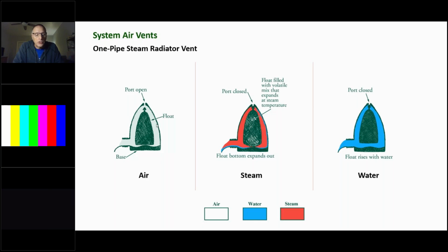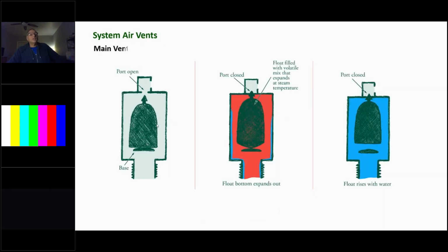If you show up and your pressure control is set at a 2-pound cut in and a 4-pound cut out, it'll start up fine on the first cycle of that boiler. As it starts up, the vent closes because it's set at 2 to 4 pounds. The vent will never reopen. The system has to cool completely for the pressure to drop below 1.5 pounds to reopen. So that's why half a pound to a pound and a half is the rule of thumb for most residential steam systems if you're not using vapor or a vapor stat. This is the same operating principle here.